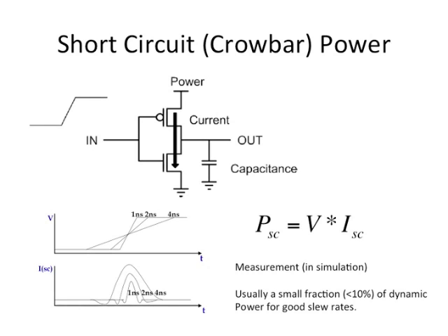Yeah, but if this lower means width is lower, that means the resistance should be higher. No, no, no. We are not changing the size of this gate. The gate is fixed, but the output load capacitance is reduced. So you have an input of a certain ramp, and the output load you are reducing, so that you see the changes. Actually here what is happening is that the input ramp is being made faster and faster.